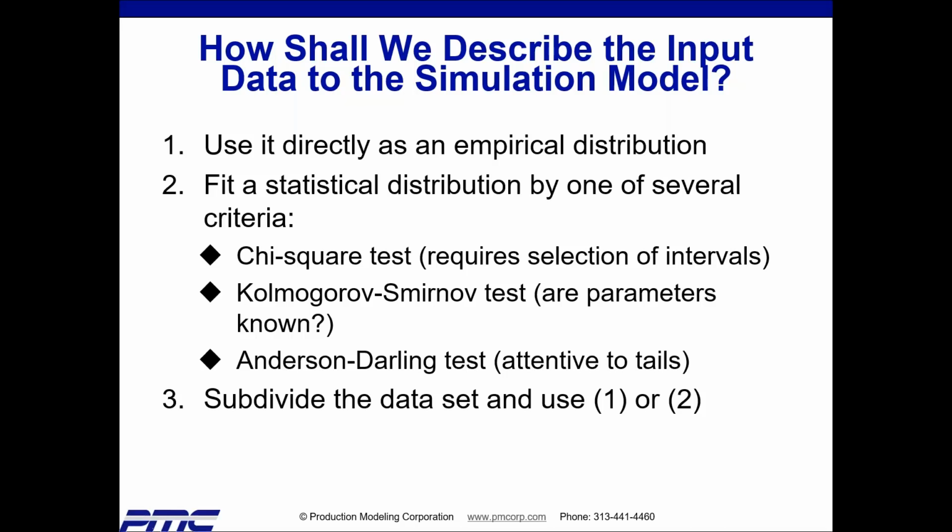Or I was collecting data on cycle times for this manual operation. I didn't notice it yet, and the user didn't think to tell me, and I didn't think to ask the user, oh, maybe that machine is doing its work on 2 or 3 different types of parts that come down the production line in random order. And it just naturally takes more time to do the work for a model A than to do the work for a model B.